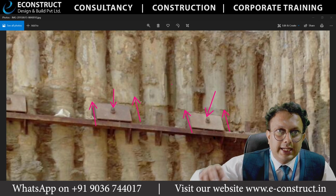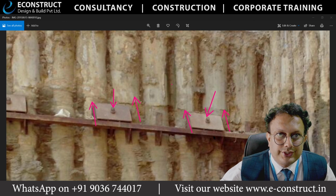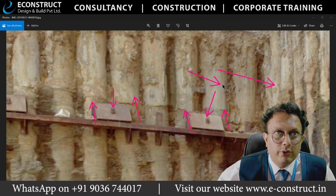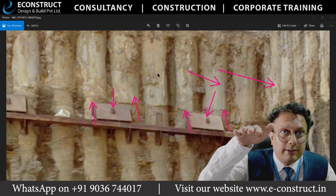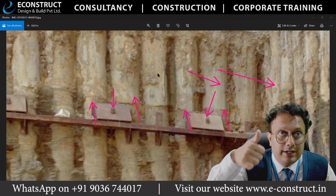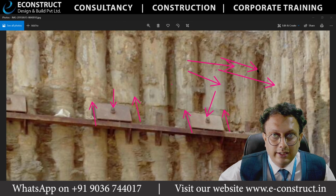Understood? So the PT strand has a lot of tensile resistance. It is given in such a way that if, for example, these piles want to come out because of certain heavy load. Imagine on the top there is a truck coming or something which is a surcharge increment, correct? If the surcharge force has increased, that force will come on this and this pile will start popping outside.